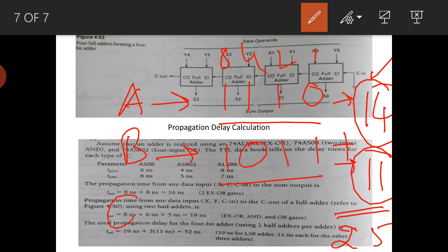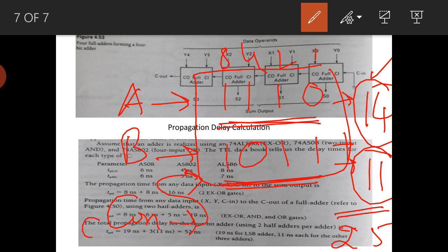Let us take carry. Suppose there are 2 variables a and b, each of 4 bits. For the module as an adder, these are 2 inputs and there is one more input, carry in, which I will take as 0. There will be 2 outputs, sum and carry out. As we know, in 4-bit addition the sum will be 4 bits only, and carry out will be a single bit.